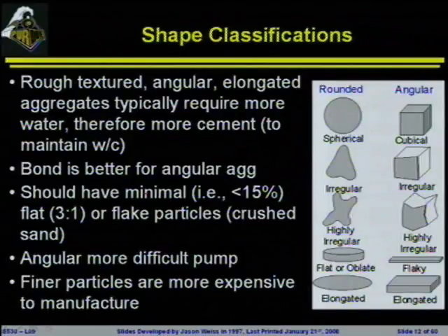This shouldn't be surprising. A smooth or rounded aggregate doesn't stick as well as a crushed aggregate. There should be minimal flat particles, and when we're talking about flat or flake particles here, we're talking about something with an aspect ratio of 3:1.